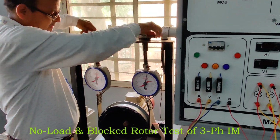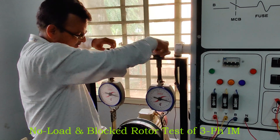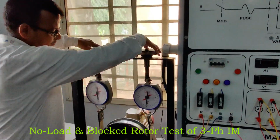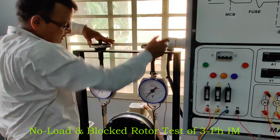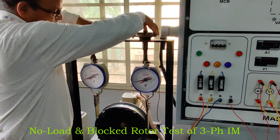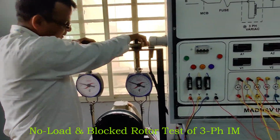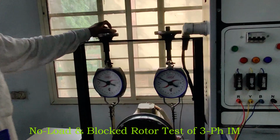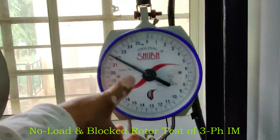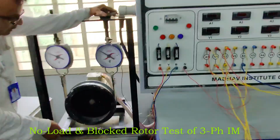Tightening the belt in such a way that this motor will not move. Tightly tight. See that it is not rotating. It means it is blocked. That's why it is called the block rotor test. Second thing, it is blocked, and its load is here. See that it is not at 0 position. It is 22 kgf and 21. So it is totally blocked.